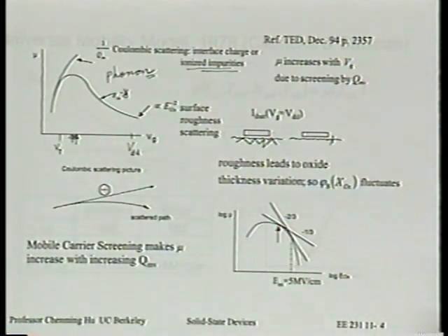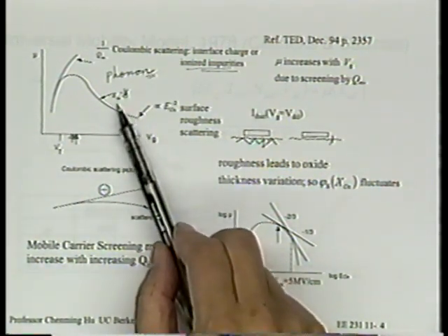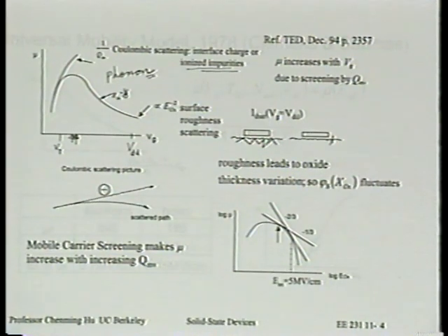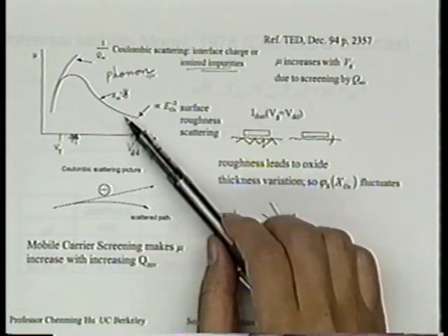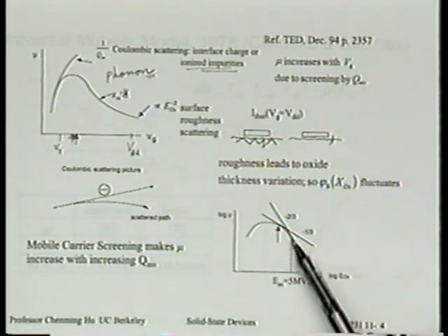But you're right. It's not necessarily meaning right at the surface, but wherever that inversion layer charge flows is the mobility. And there you can already see why there are so many explanations for this VG dependence, because where the current flows also varies with VG. So plenty of reasons. Let me just finish by saying, I wouldn't be surprised if more and more we'll be able to explain these by phonon scattering as well.